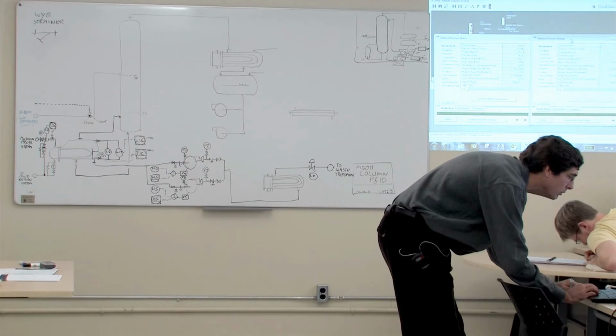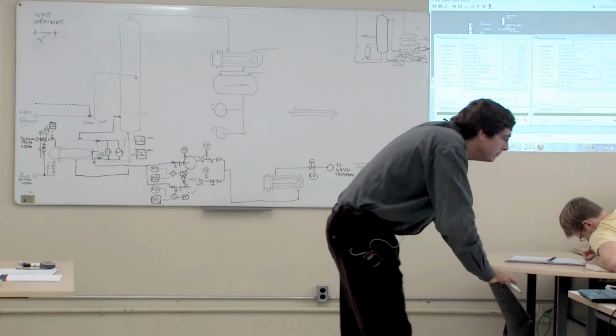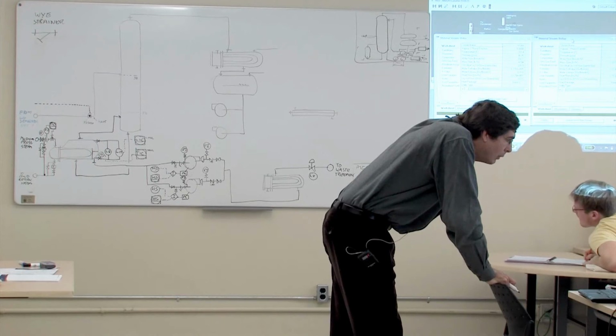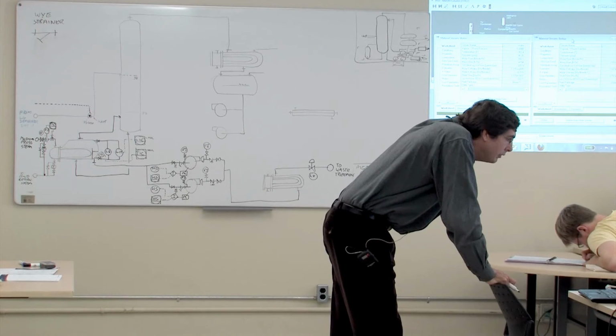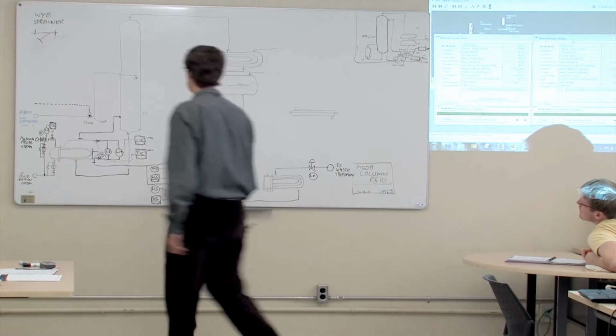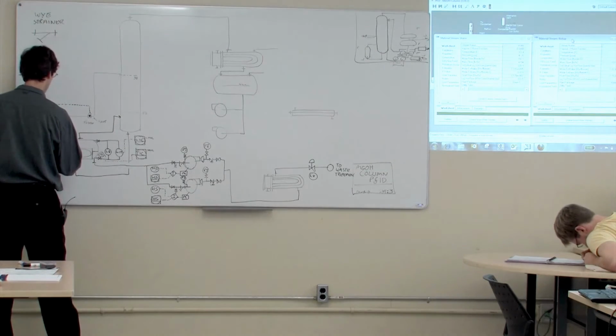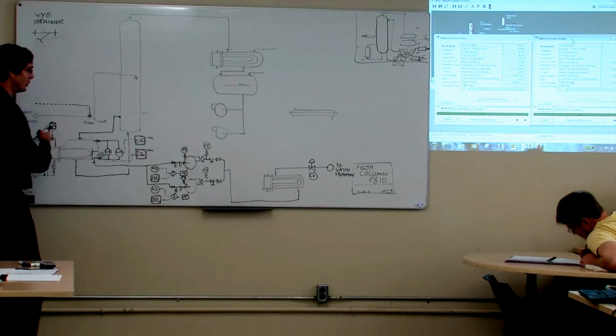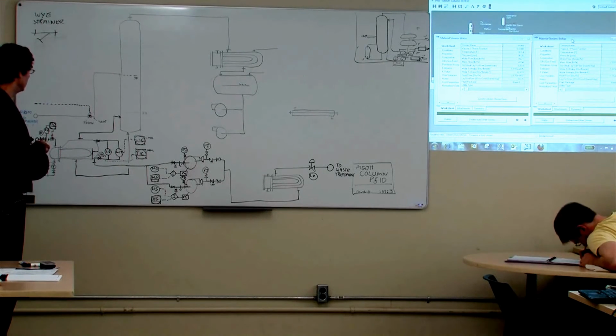So you compare those, 5,000 versus 20,000. They're different, but we could probably get away with doing either control scheme. But for now, I think we should put the level control on the higher flow rate, which is the boil up. So let's do it. What I have to do is get a signal from there to there. That's two controllers talking, so I need a software signal.